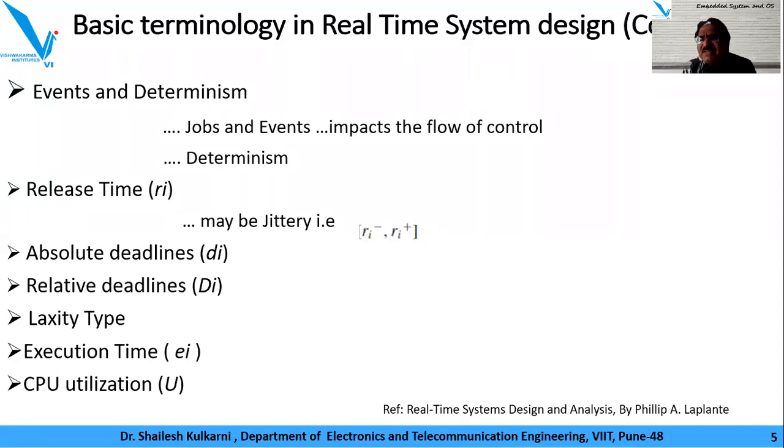So state machines are the perfect example of how a system can be made deterministic. In state machines, we have a predicted output, an estimated output, for every set of inputs, in relation to the current state or maybe a previous state, isn't it? So that derivation of the output state is highly deterministic, and that is why FSM is referred to as the most accurate way of deploying a system in real time.